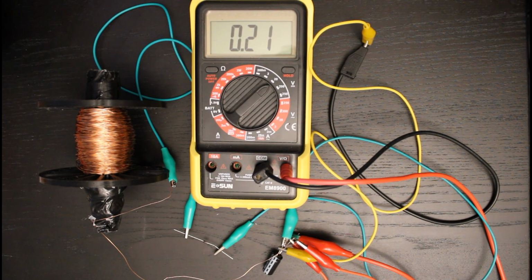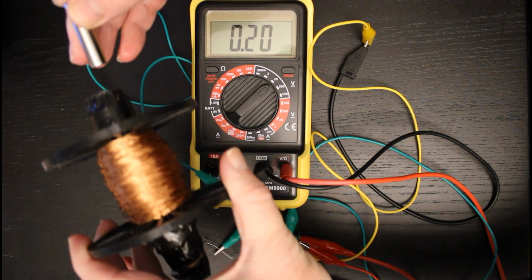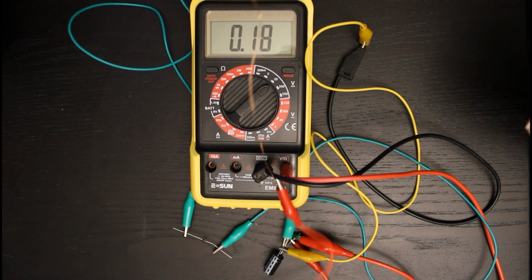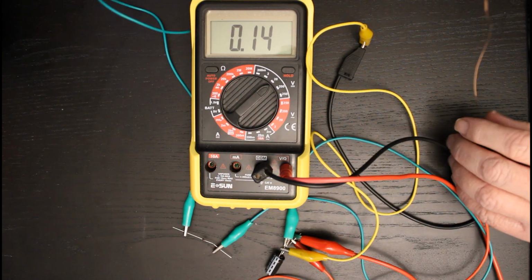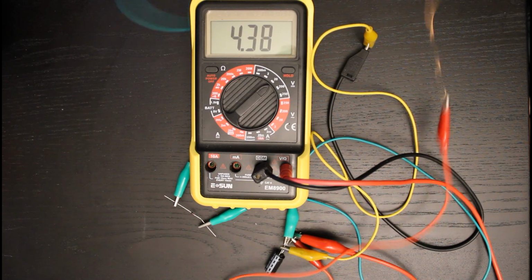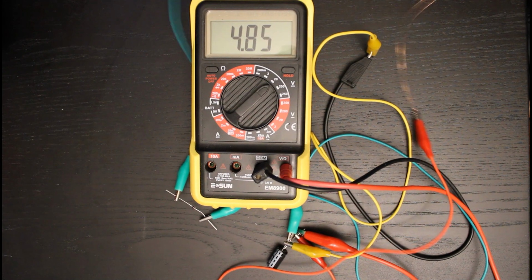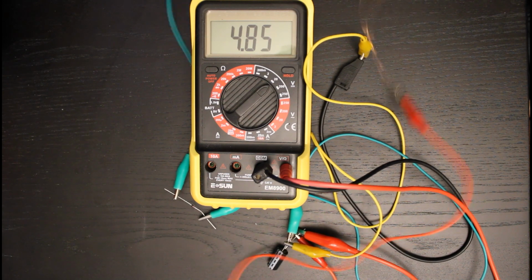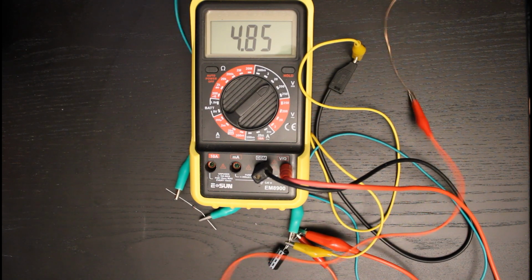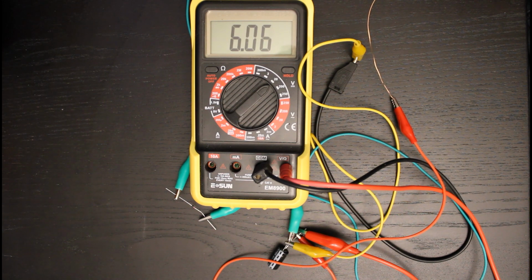We've got a very tiny residual voltage there, nothing to speak of. So let me insert the magnet into the coil. And now, if I can do this, hopefully without dislodging any wiring, what you should see is a voltage accumulating there. So we're getting quite a healthy voltage accumulating in the capacitor, which is great. It doesn't look like I'm going to get much above slightly shy of 5 volts there. But that'll do just to demonstrate. Oh, look, now that I've stopped.